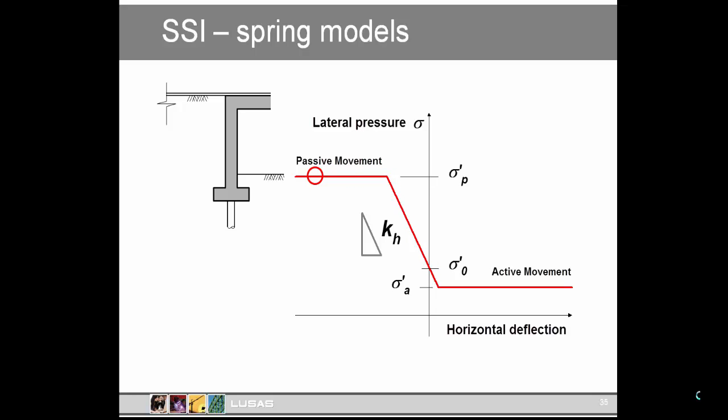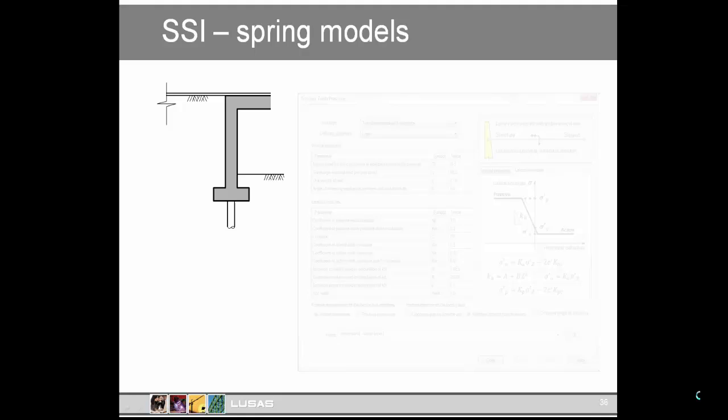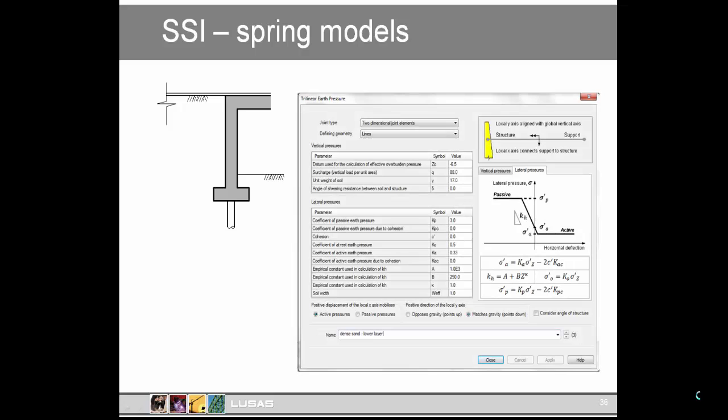Now, with the at-rest pressures varying with depth and the limiting pressures varying with depth and the spring stiffnesses varying with depth, as we discussed with reference to springs with piles, there's a lot to keep track of. And since there may be a need to modify these values to take account of ratcheting, the software should give you control over all those parameters. Flexibility, but also some means of defining the various parameters in a way that is comprehensible and controllable.